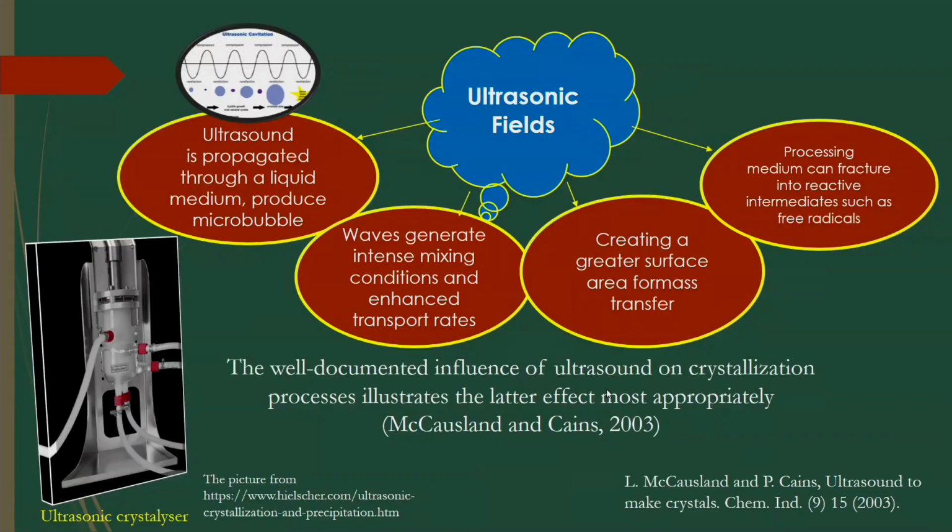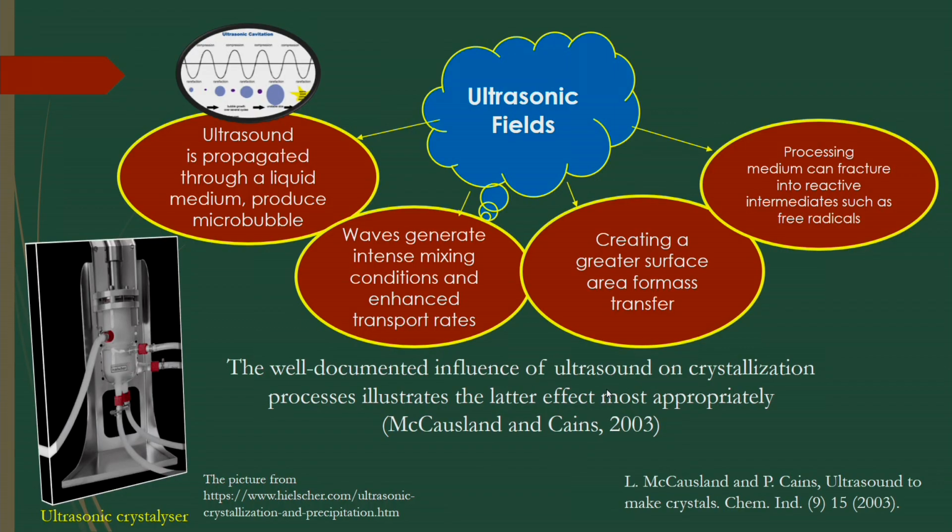So, in this way you can use ultrasonic waves to create finer droplets to extract propionic acid from the water. That is why intensification is based on ultrasonic fields for this particular extraction operation. Even the processing medium can fracture into reactive intermediates such as free radicals also. Sometimes if you use micro bubbles, even nano bubbles, you will see it in the ozonation process. Nowadays intensification of wastewater treatment is by advanced oxidation, like the ozonation process.